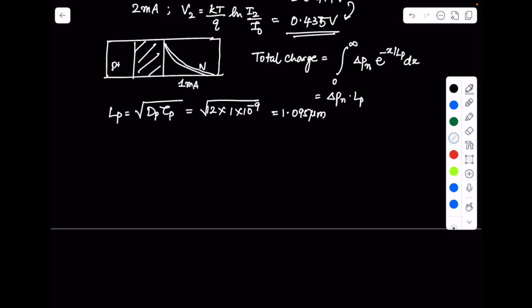Instead, I know what I naught is, right? So now if I think about I naught in our diode, again, we're assuming it's all uniform across. So the I naught can be given as Q times Dp by Lp into Pn naught. This is a P plus N diode, which means I don't know the doping concentration. Because I know I naught and because I know it's a P plus N junction, I can calculate my Pn naught to be Lp by Dp into I naught by Q, right?